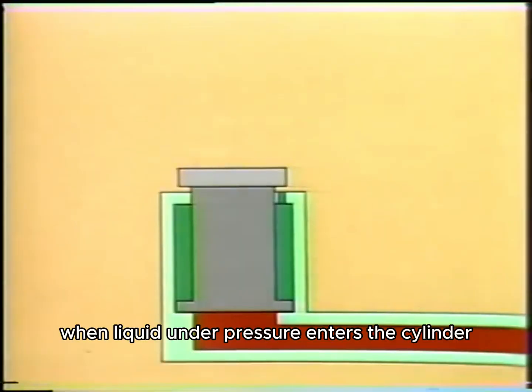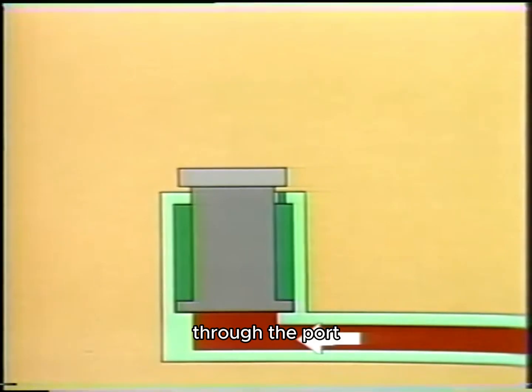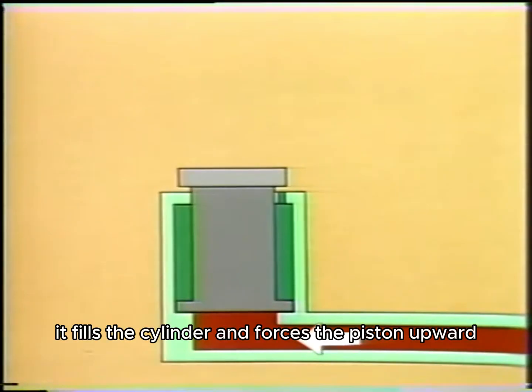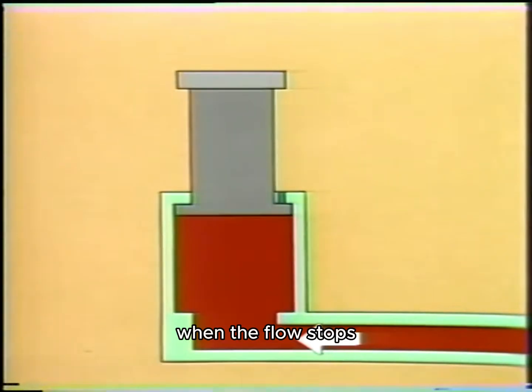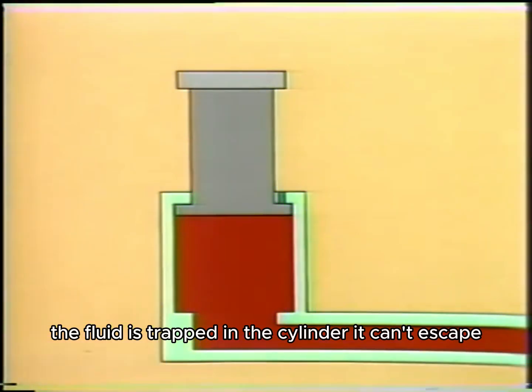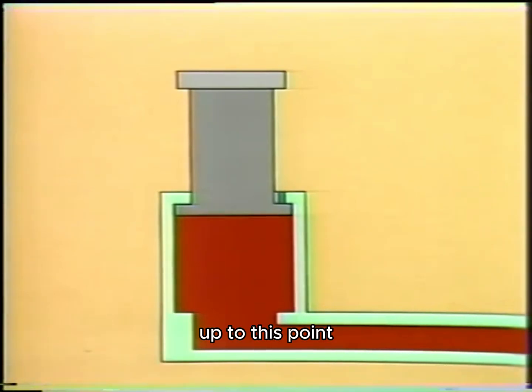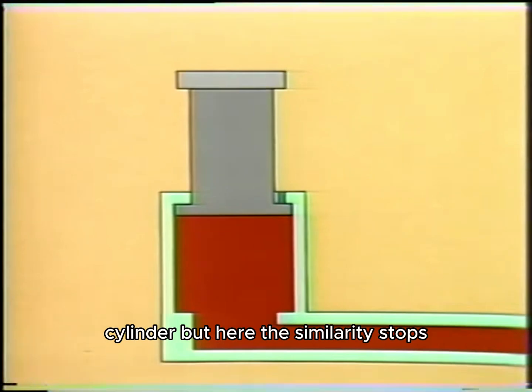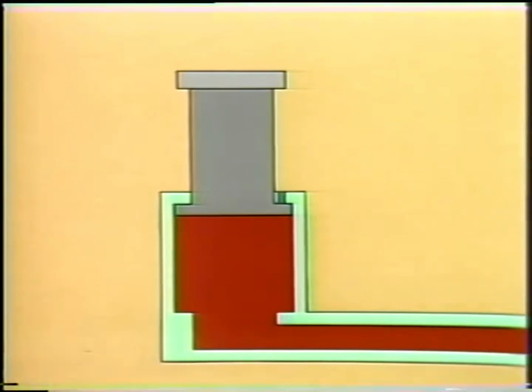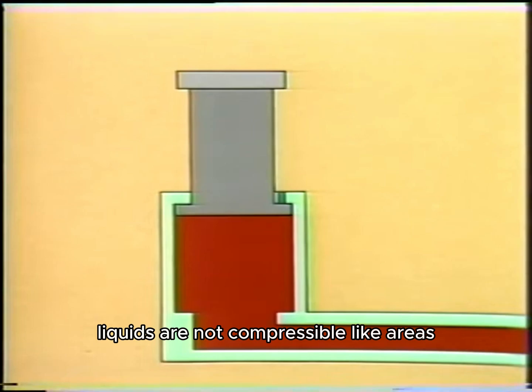For example, when liquid under pressure enters the cylinder through the port, it fills the cylinder and forces the piston upward. When the flow stops, the fluid is trapped in the cylinder. It can't escape. Up to this point, the situation is similar to that of a pneumatic cylinder, but here the similarity stops. Liquids are not compressible like air is.